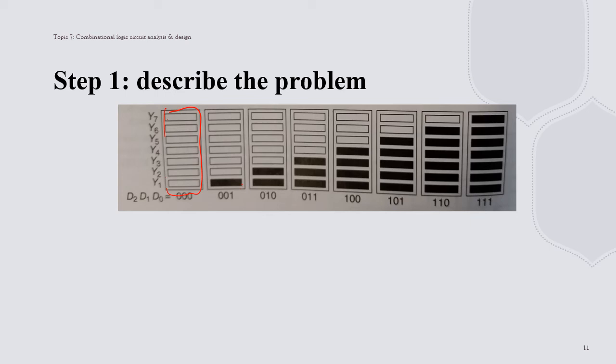Since we have 8 different states, how many control lines do we need? If we think about what we learned in the second lecture, right? The binary number, the combination. To reach 8 states, we need 3 control lines.